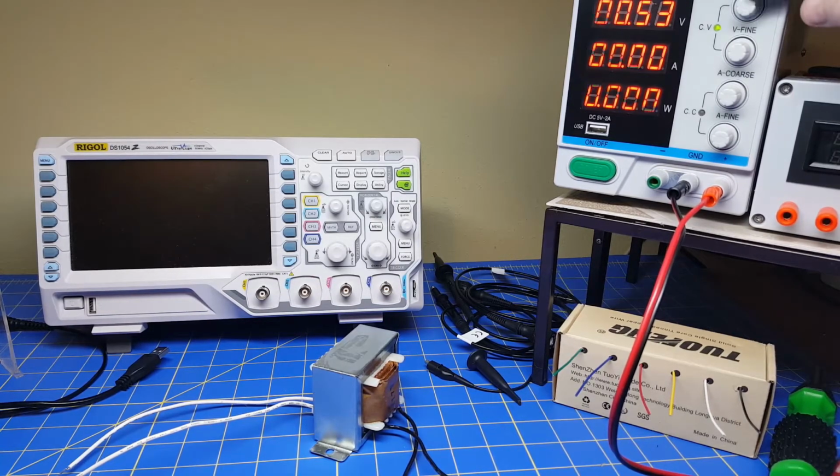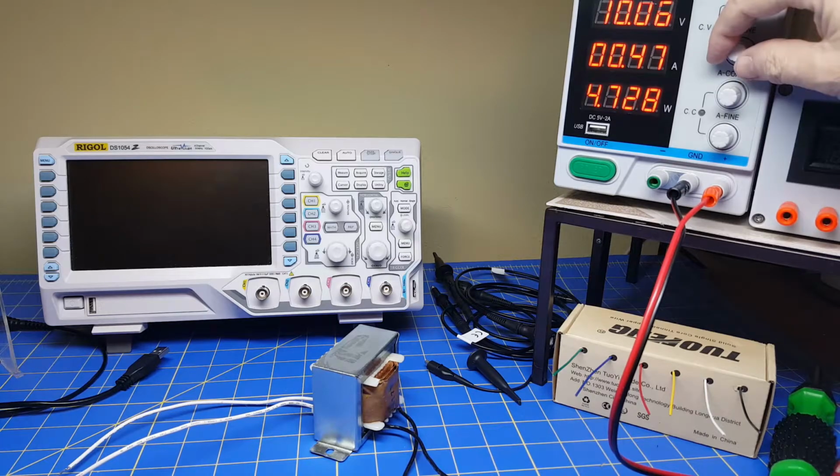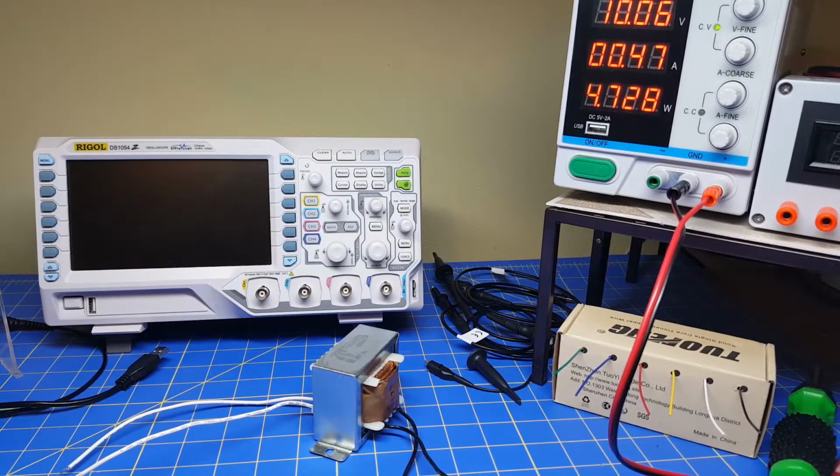Okay, so now I'll use another method to check the primary resistance. I've got it hooked up to my DC power supply, and I will crank this up. And when I get up around 10 volts, I'll expect, if it's 20 ohms, it should be half an amp. So I'll go up to 10 volts, 8, 9, so 10 volts, about just under half an amp. So that makes sense if it's 20 ohms. So they both check and they both match what we expected.